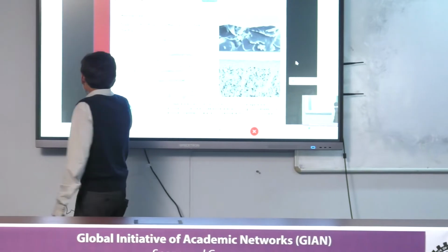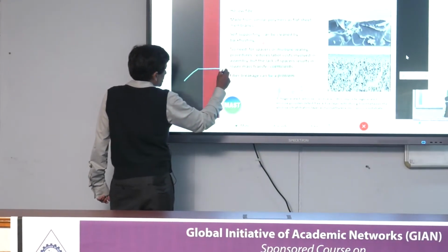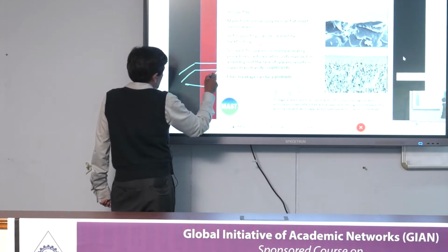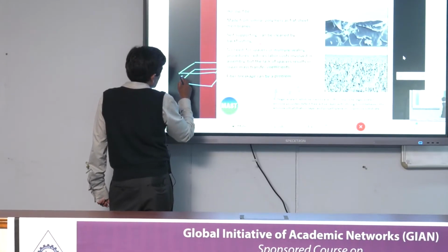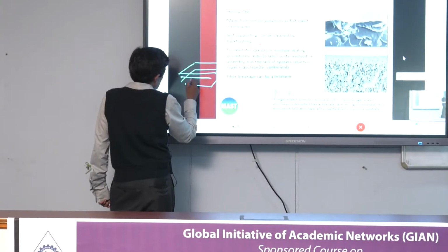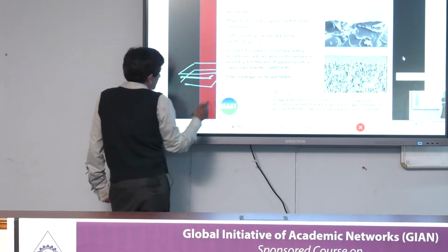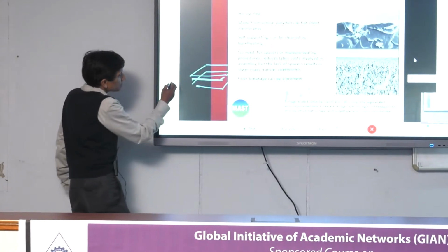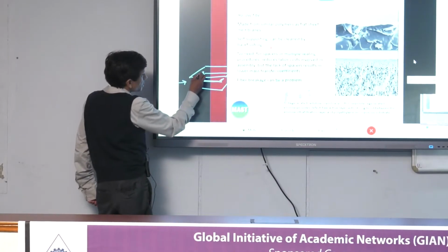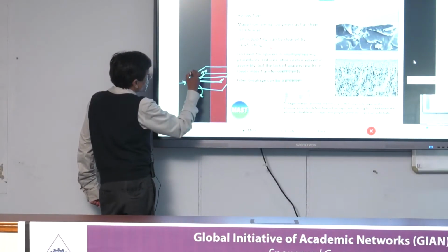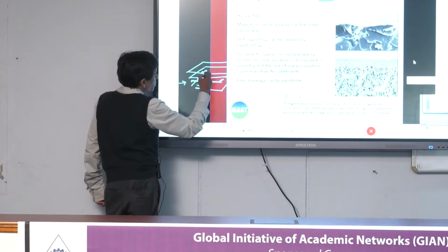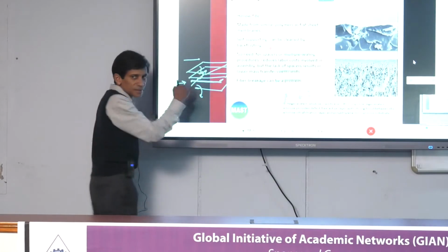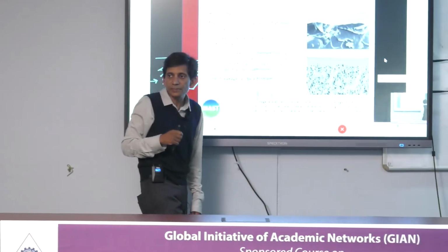If you use a flat sheet membrane, you may have one membrane sheet like this, and then you have another membrane sheet like that, and in between them you have to have a spacer. This is our spacer layer, because you don't want these two membrane sheets to collapse on each other. Your feed will come through here, and you can withdraw permeate from here and from here, and then typically you have another membrane layer on top of this and a feed coming here with another membrane on top of that, and permeate from this one comes in there. So you have alternating feed channels and permeate channels.